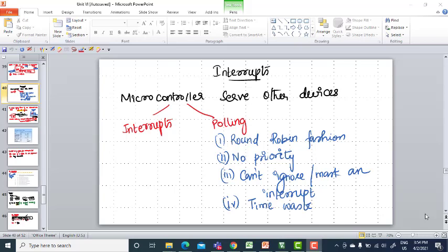The 8051 will service only one interrupt, and then it will ignore the rest, meaning it won't consider the next. There is no priority when it comes in a round robin fashion. Whichever is first encountered will be serviced first. And moreover, all the other four interrupts will be in a waiting list. You cannot ignore or mask the interrupt. Only if you have a priority, the higher priority will be done, and the other four will be masked or ignored.